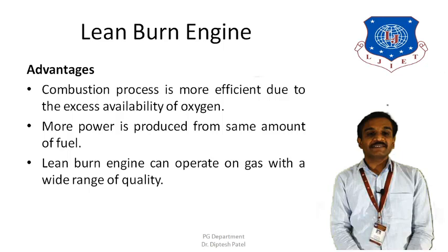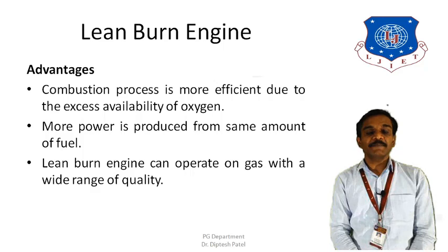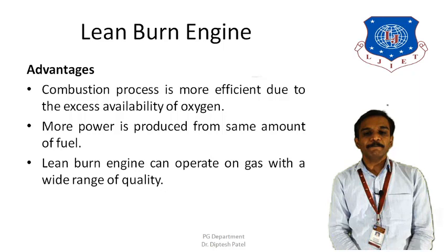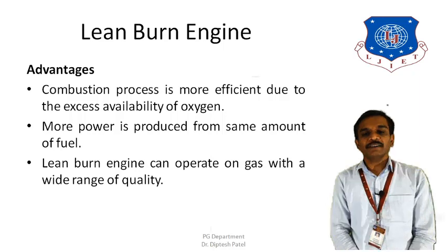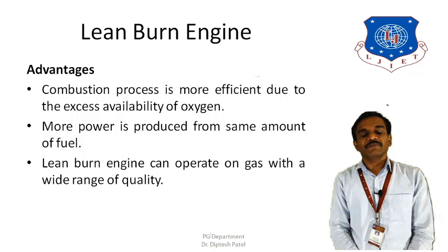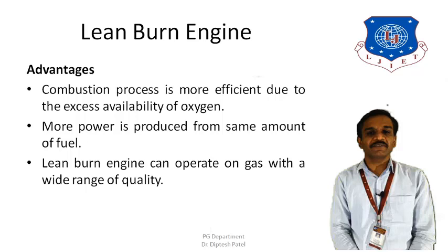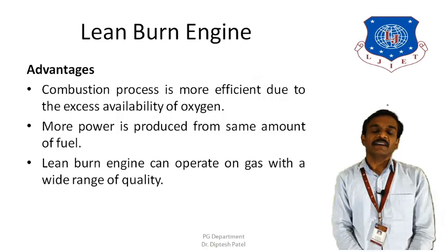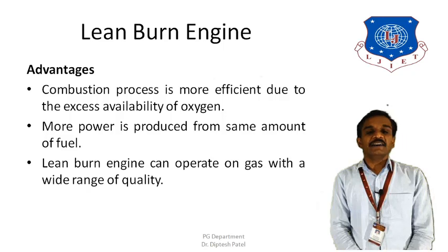However, there is one demerit of the lean burn engine: the emission of NOx is enhanced because the combustion temperature is very high, and therefore we require a complex catalytic converter to reduce the NOx emissions. This is the only drawback of the lean burn engine, in which the NOx emission is higher compared to the conventional engine. However, other emissions such as HC, particulate matter, smoke and CO are reduced greatly compared to the traditional IC engine.